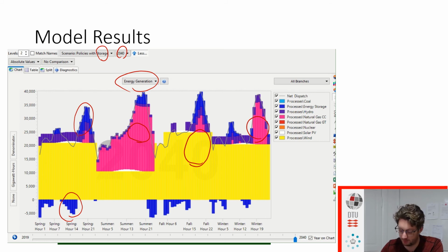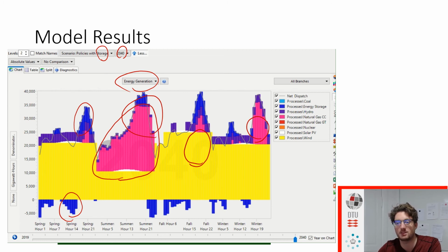We can also see in this case, which is quite interesting, and that we probably wouldn't see otherwise if you haven't optimized, that our summer months are very dependent on our natural gas combined cycle, and we use quite a lot of energy there in some of the peak hours. So we could probably do a lot of different investing or de-investing in that if we could somehow demand side manage, or use DSM, on our air conditioning, for instance, our big loads in the summer months.